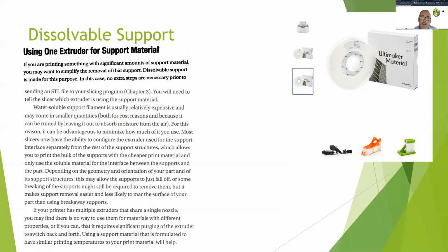It's almost like a hard Elmer's glue that will be extruded in the points that would be removed or would not be needed, because you can't just print in midair. And so you have to have each of these layers built up one at a time. It builds the layers for the dissolvable material like it's shown, and then you take the model and put it into a tank. The tank has an agitator in it and a warm bath, and then it will dissolve the dissolvable support material.